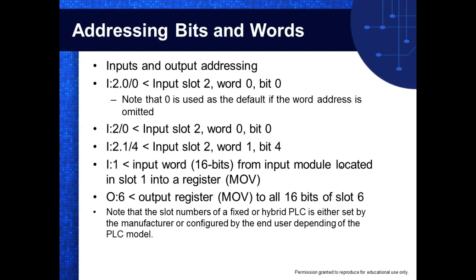Siemens, I'm not sure. We got some 1500s over there that have a slot. I need to research that a little bit. Normally, the slot number is not built into it. You have to configure it with software when you install it. You have to tell it what slot it's in. Everybody okay?